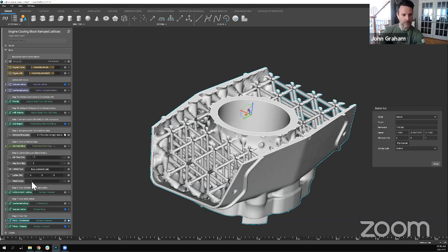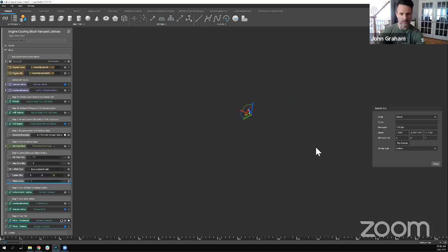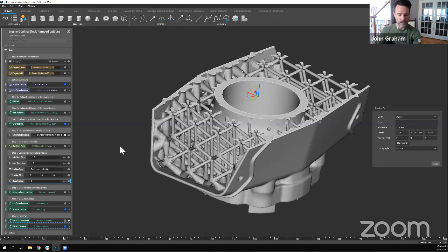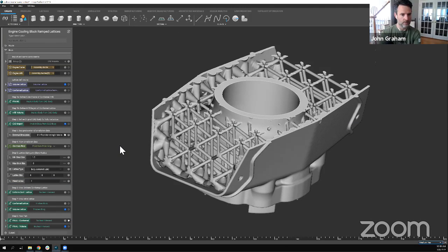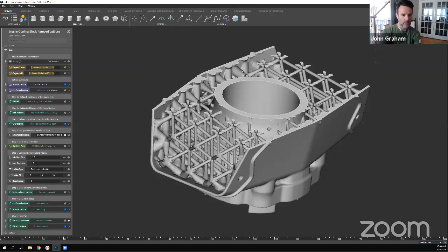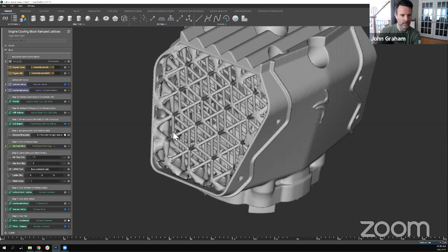Now, this might be a decent time to show off what this blend radius does. Let's drop that to 0, and you'll see wherever the struts start to intersect the body, you have no more radius. Now, this is where if I went to a higher resolution, you would see something that looks a bit more realistic. Let me just do a couple of undos and redos. Okay, here we go. So you can see kind of a larger radius where the struts meet the perimeter around there. Now it's a bit smaller, and I realize it's confusing if I'm going from cross-section to full view, but you really don't see as much of a radius. You see a little bit, and that's just the rendering issue. But if I go back to 2, yeah, it's a bit bigger over there.